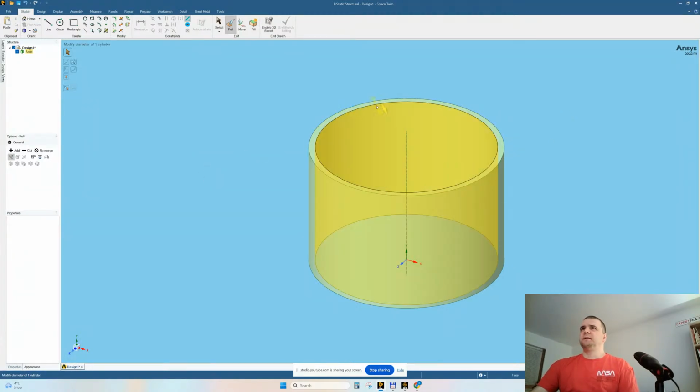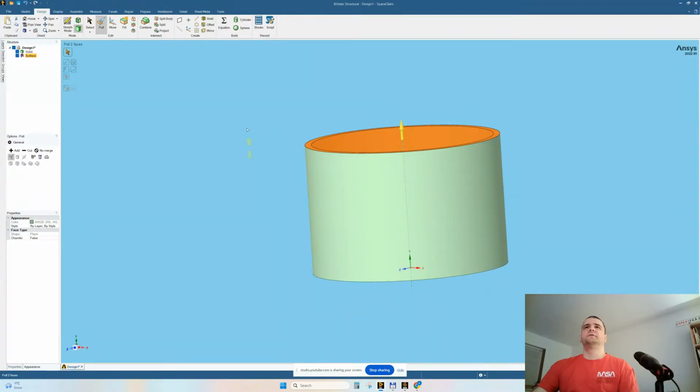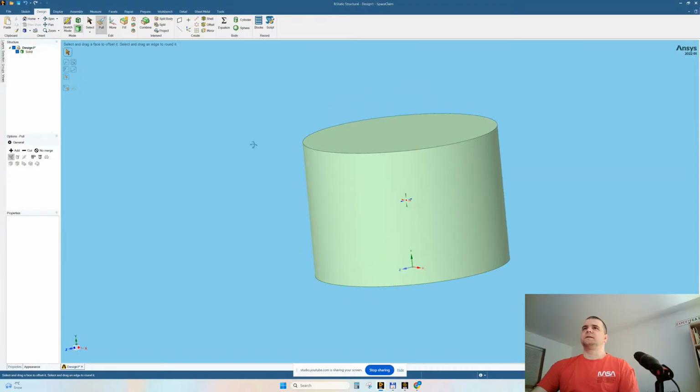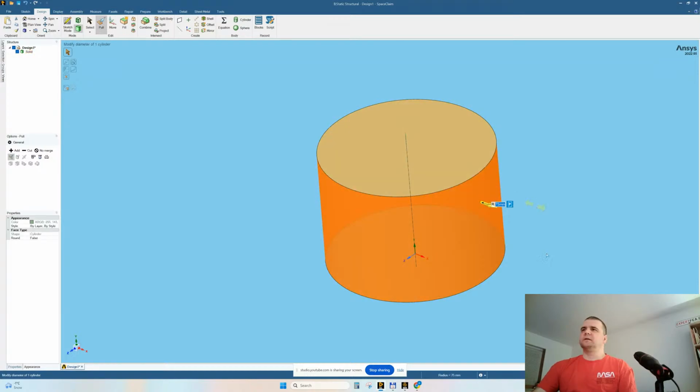So it needs to be kept somehow, to have a cap, yes? And let's go here, design fill. So this face is filled, and we're going to pull with, I don't know, maybe 5 millimeter, something like this, all right? And you can see it. It's something very basic, because in theory you are interested only in the contact, in the heat dissipated between this surface and the inner face of the cylinder.